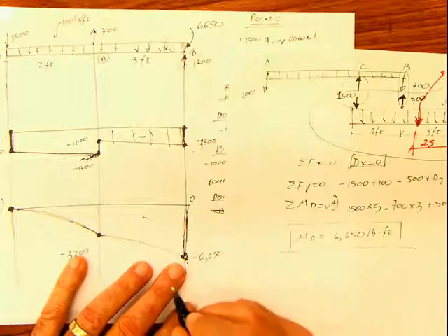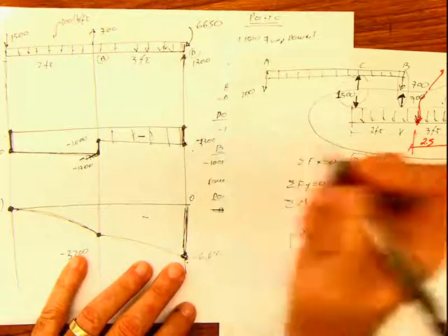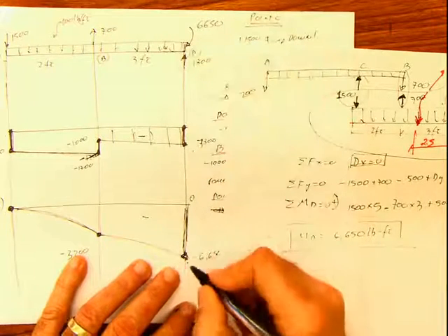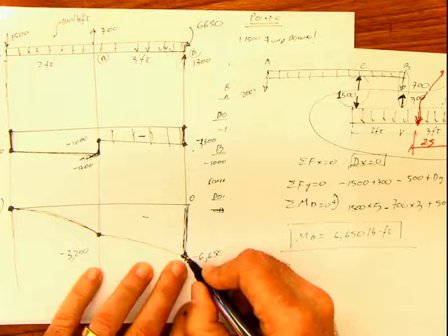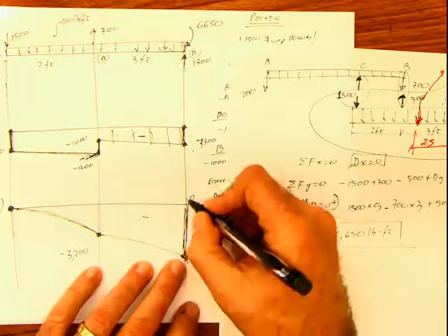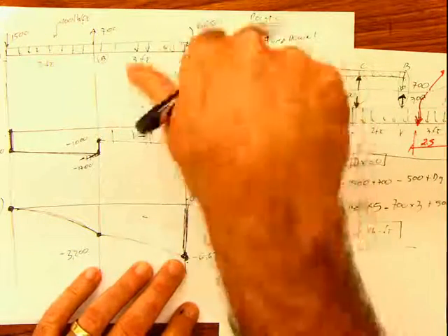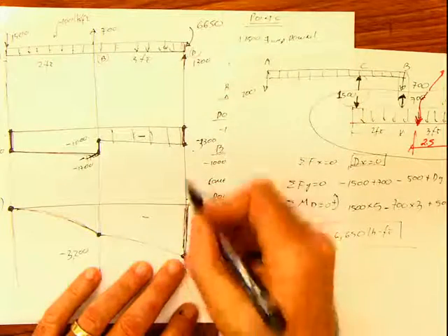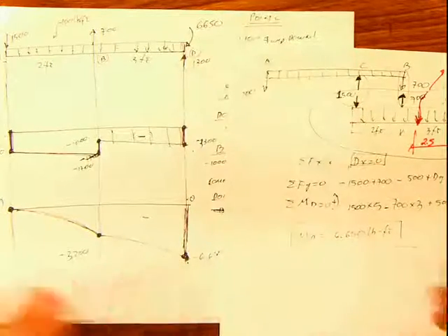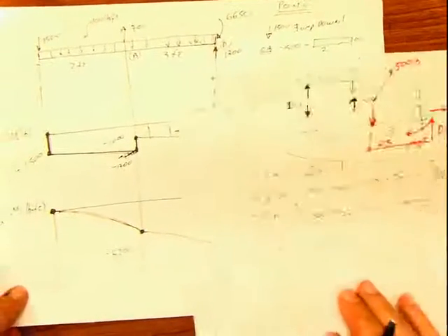It's the only possibility. So that's the value of the reaction. Same thing here. If I'm at a negative moment here, the only possibility for closing in 0 is to find in the beam a positive moment, which in this case is counterclockwise, acting on the beam, and that was the value of the reaction.